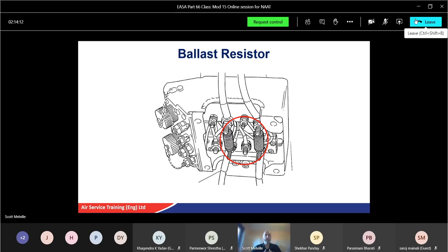The pilot doesn't want to see 4 gauges, one engine reading 598, one reading 601, and one reading 597. He just wants to see 4 gauges, maximum throttle, 600 degrees. That lets him know that all engines are working correctly as well. The actual temperature will vary for each engine, but the ballast resistor compensates for that.